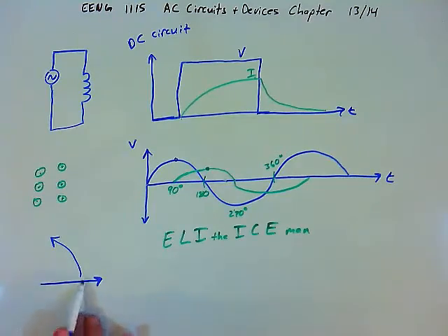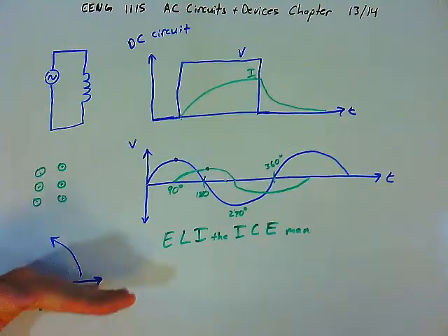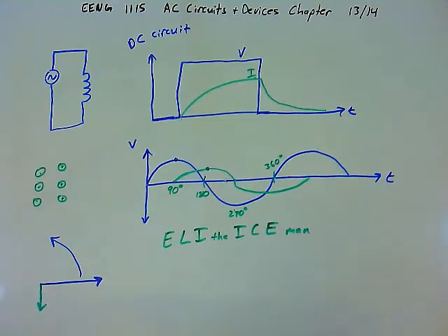Now, the voltage comes first. It's rotating. It's going counterclockwise. And it is leading the current. And so the current is a vector that is 90 degrees behind. And so as these two are rotating, we have the voltage and the current, and the voltage is leading the current, right? The longer blue vector, which is the voltage, is leading the current vector. And it's leading by 90 degrees. And that will be the case as long as the circuit is purely inductive. There's no resistor in the circuit.